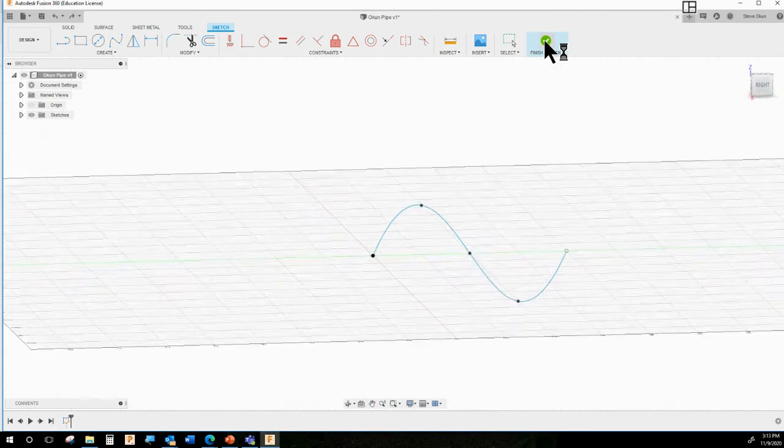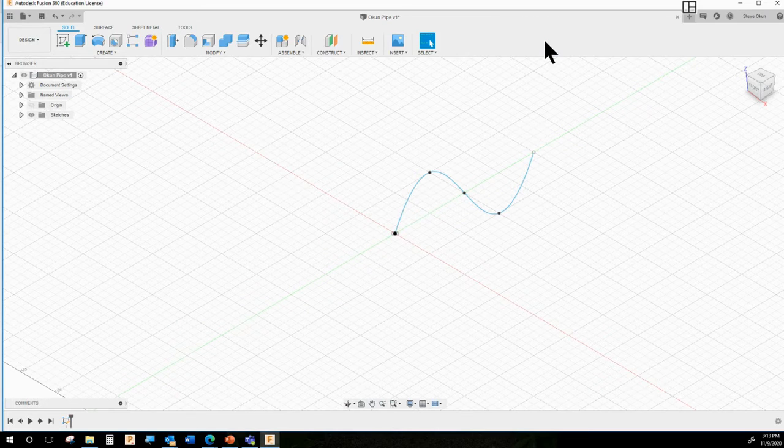So you need to finish this sketch and create a new sketch to make the cross section. We're going to make this a pipe, and the hollow part of the pipe will be 10 millimeters in diameter. Then we're going to make the wall of the pipe about 2 millimeters, so it will be 2 on either side.